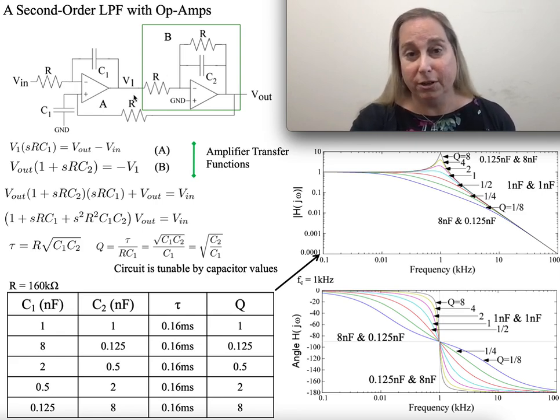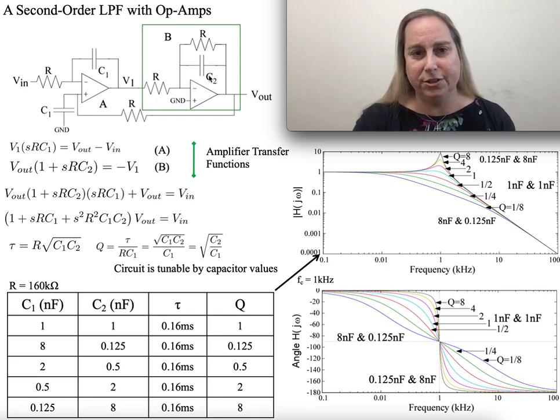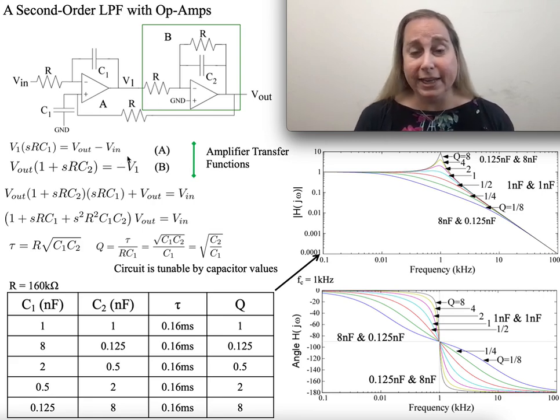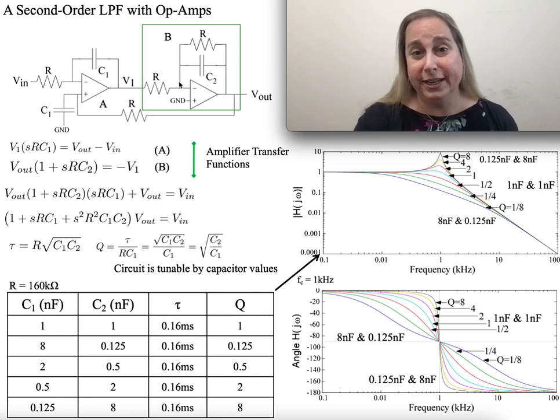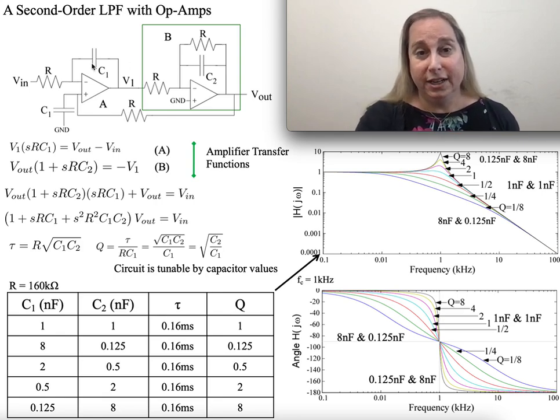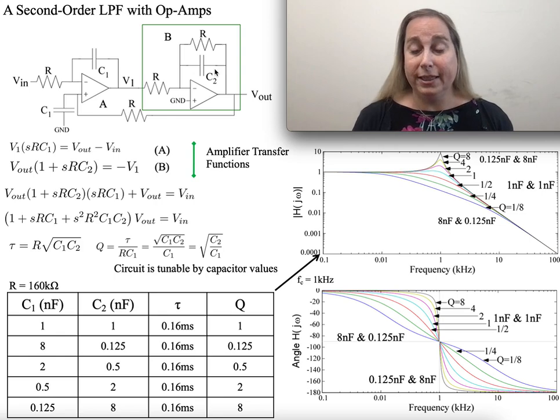The second one, this is a low pass filter, gain of 1, so I would expect this is going to have R and C2, and then minus V1 because it's coming into the minus terminal. Again, if you're not sure how to do that, you just write KCL at this node, realizing this node's basically a ground, and you can pretty much solve it straight up in terms of what the time constant behavior is, knowing that, of course, C1 and C2 I think of in the Laplace space. That's why there's the s in front of it, because it gives you a Laplace transformation.